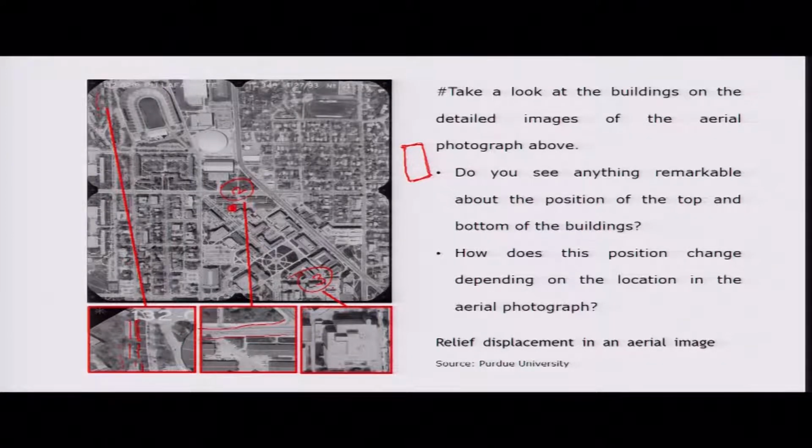In window 3 you can see this building very clearly. Okay. So, you can see the base of this building here and the top of this building here. Okay. So, this is another advantage of the vertical aerial photograph. We can calculate the height of the objects by applying the relief displacement in addition to the flying height, that is capital H. I will explain on the next slide.